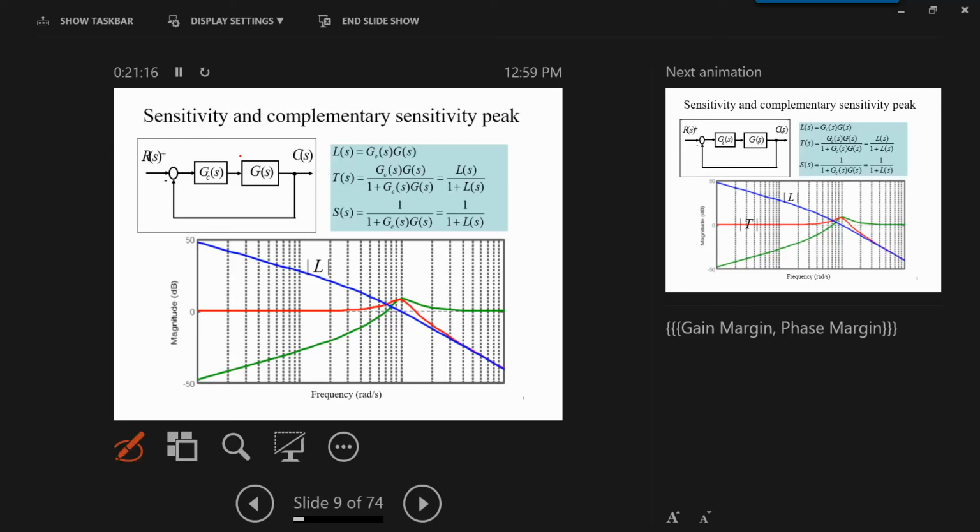The slope is minus 20 dB. How did I know it is minus 20 dB? Because if I extend the slope here, this is approximately 2 decades, and we are getting approximately 40 dB over 2 decades, so minus 20 dB per decade. So this is a type 1 system, and I know that for a type 1 system the steady state error to a constant input should go to 0.